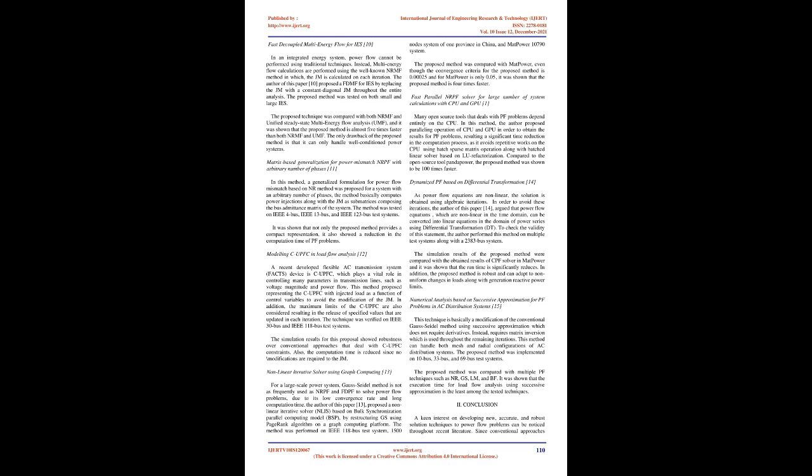The only drawback of the proposed method is that it can only handle well-conditioned power systems. Matrix-based generalization for power mismatch NRPF with arbitrary number of phases [11]. In this method, a generalized formulation for power flow mismatch based on NR method was proposed for a system with an arbitrary number of phases.